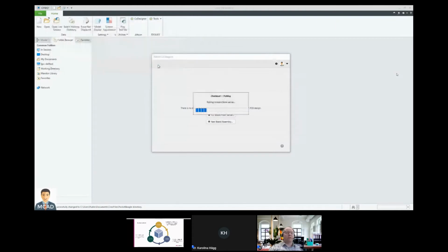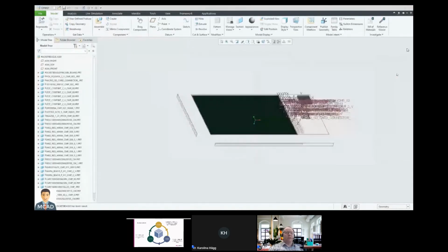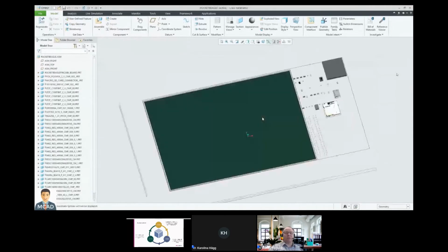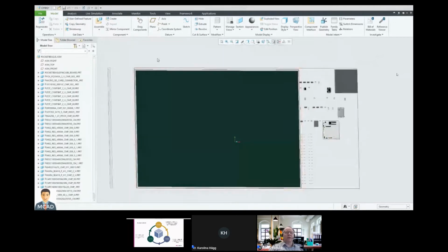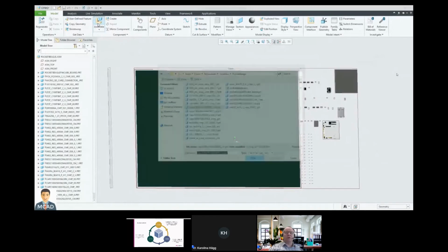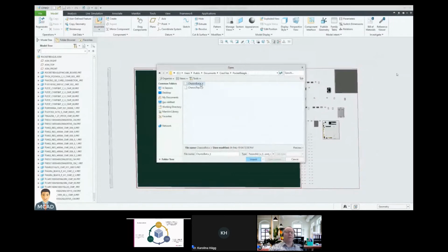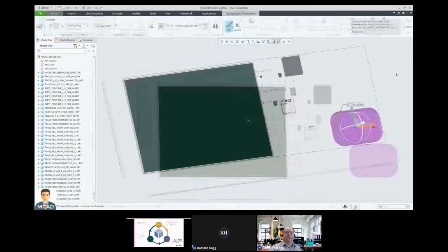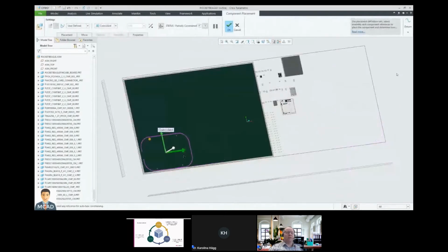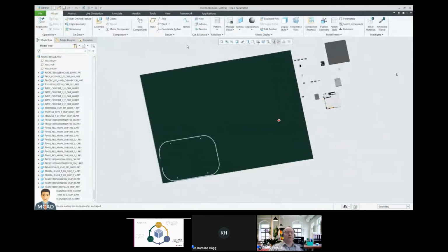Creo Parametric this time is creating a new 3D assembly from the information from Altium Designer. As you can see, the PCB board is just a flat surface, and then we have the biggest components just placed there, and now the mechanical engineer needs to start modifying the design by creating the right shape for our board. He's importing first the enclosure where the board needs to fit in, putting that in place and then modifying the board geometry so that it fits into the enclosure used this time.